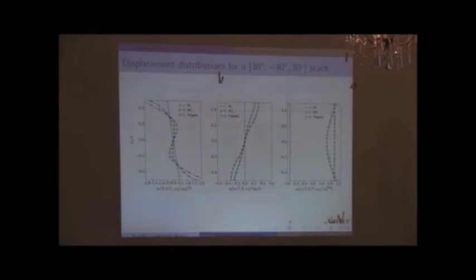Okay, so these are the shear warpings which we derived with the asymptotic expansion. That's where they are coming out. And once the plate is converged, the normal is getting straight, it follows the slope, and it's almost straight. And this is a higher order contribution. It's not scaled the same way. So this is just a warping in the infinite direction because of the couplings.